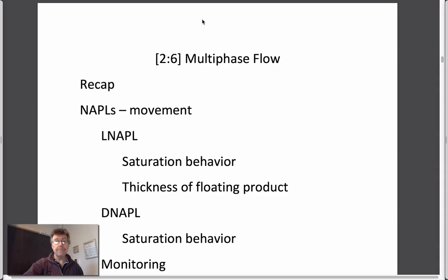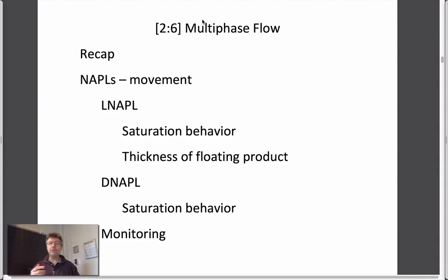We spent last time talking about the rationale of how we would identify saturation profiles with depth, and also how we could do some calculations, what I always call back-of-the-envelope calculations, and the students laugh at that, to be able to calculate, for instance, flow rates of different fluids, either water flowing through the system, NAPL flowing through the system, or contaminant loadings being the product of water going through the system with the dissolved charge of the contaminant superimposed on that. And so it was all to be able to understand behaviors with multi-phase flow.